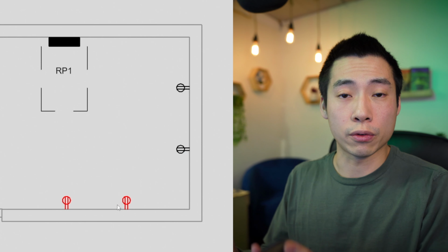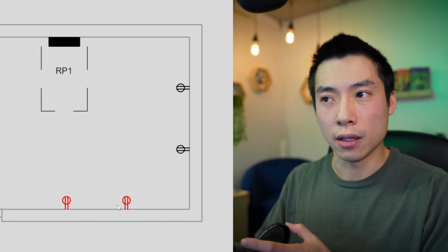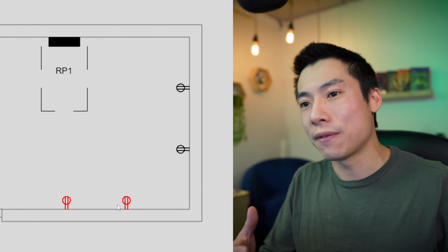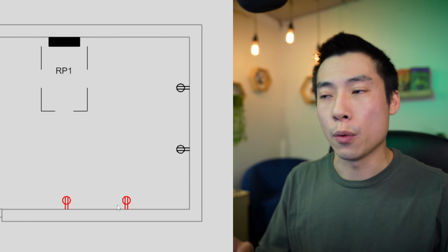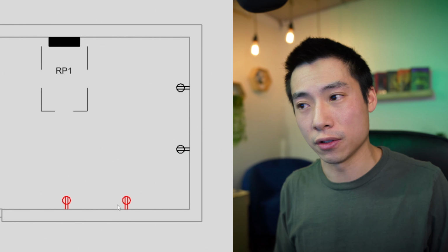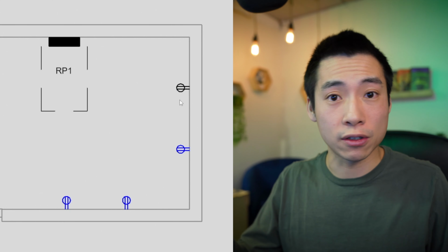So for example, if you put something from the electrical fixtures category into a lighting workset, you can have the fixture turn red. If you have a piece of equipment that is just not circuited, you can have that turn a different color. So with all these tools combined, you can use filters to greatly help your workflow and make sure that the work that you deliver is spot on.